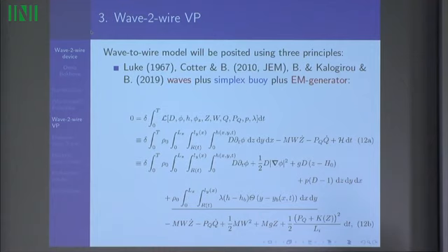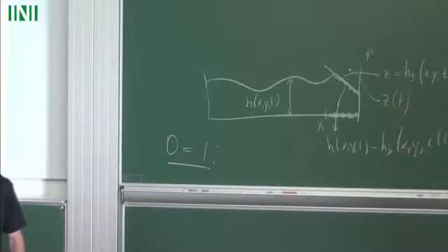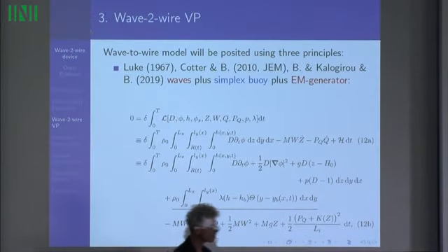Now another constraint you see here is the Lagrange multiplier, the pressure, which is multiplied times d minus 1. So in other words, this pseudo density is 1. That says that the water is incompressible. But rather than substituting that in the variational principle, which I can do, we didn't do that.